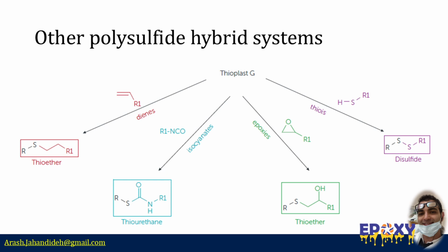The resulting products benefit from improved chemical and solvent resistance, excellent weatherability, and strong adhesion properties, making them highly durable in demanding environments. Isocyanate-cured polysulfide sealant systems in particular offer notable advantages over those cured by oxidative mechanisms. These include superior adhesion to plastic substrates combined with high elongation and tensile strength, which translates to more resilience and long-lasting seals.